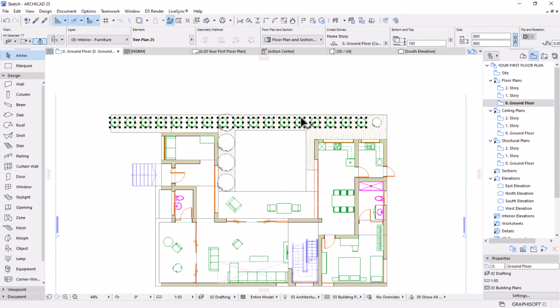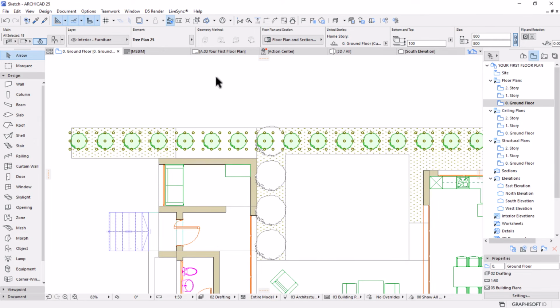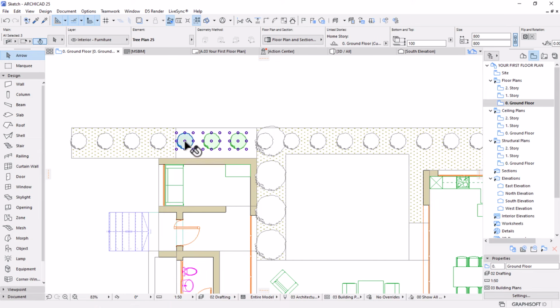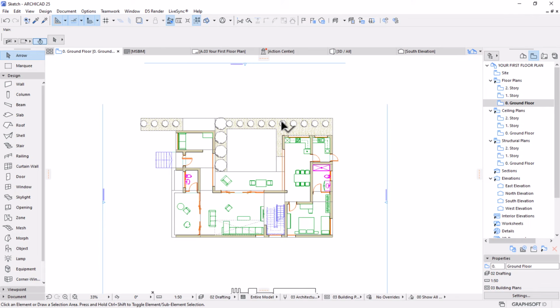Make sure you take advantage of the selection and add this one, then group, Control G. It's always advisable to do that. It's a best practice because these are repeated elements, and for future editing purposes you need to group them for easy selection. So I can suspend group and then I can get rid of this section, and this one as well.